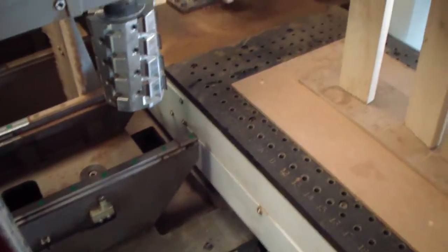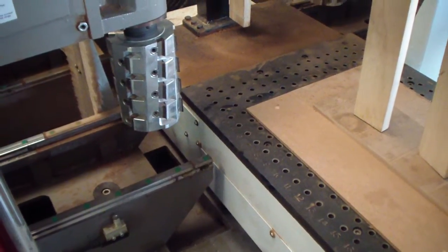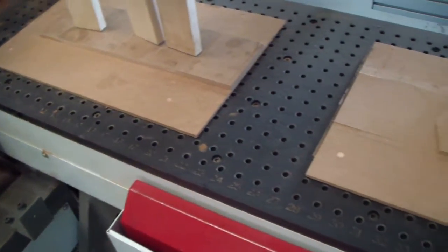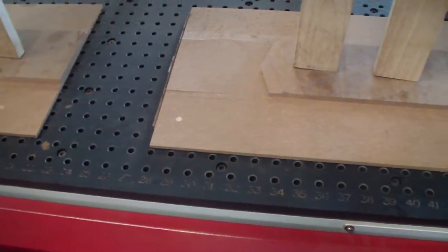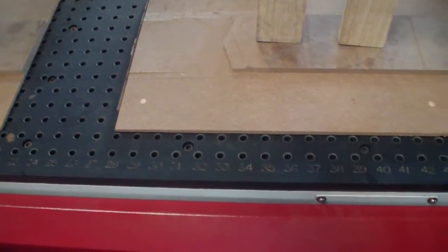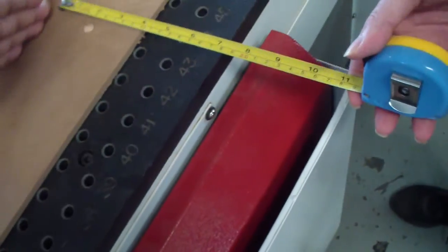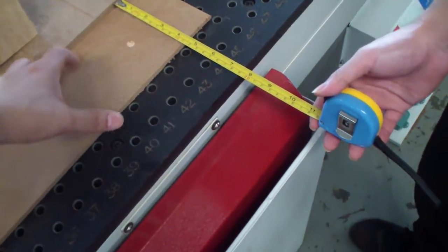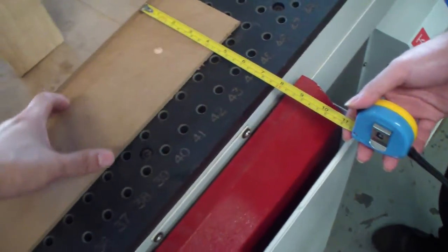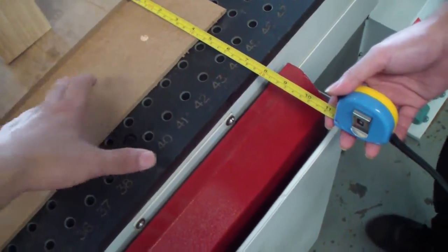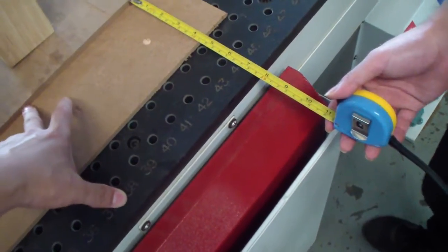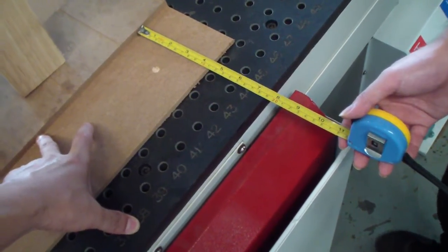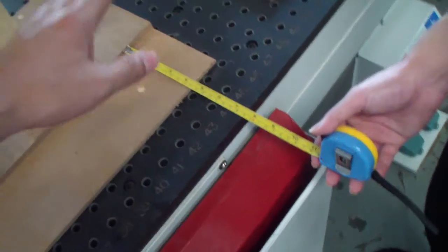After the first cutter calibration, we will do a real production. For example, we can prepare a program and make a straight face milling. In the drawing, maybe I want to mill a face from here to here, the distance is 190 millimeters.